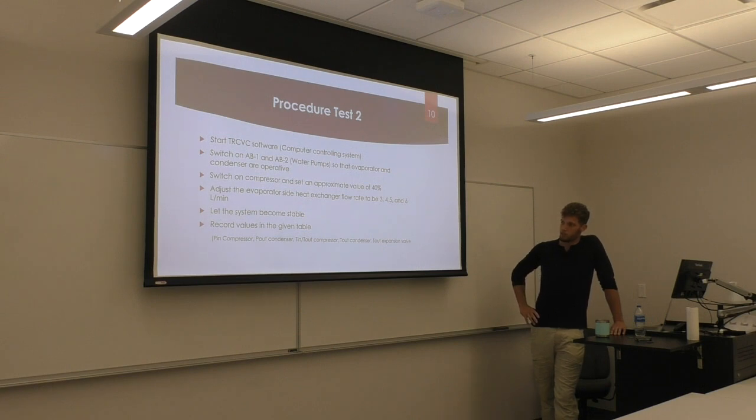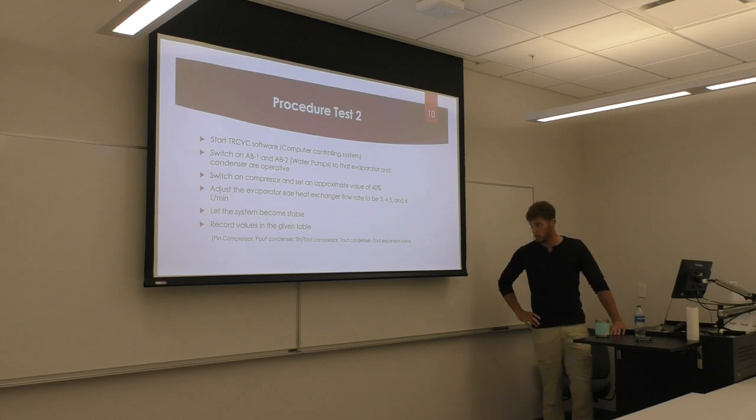And this time we want the pressure into the compressor, we want the pressure out to the condenser. We want the temperature in and out of the compressor. We want the temperature out of the condenser, and then we want the temperature out of the expansion valve.